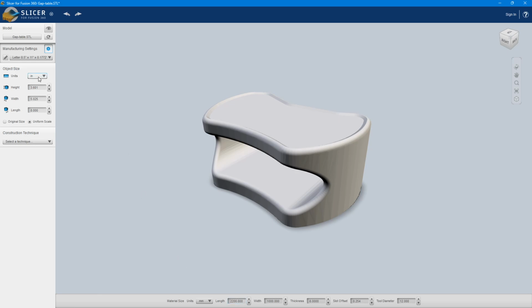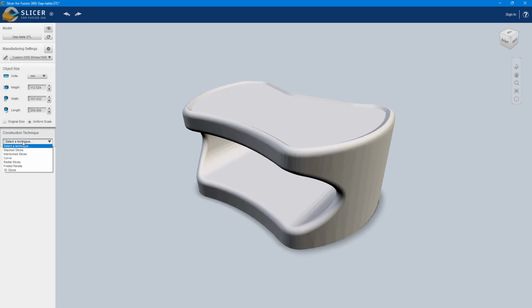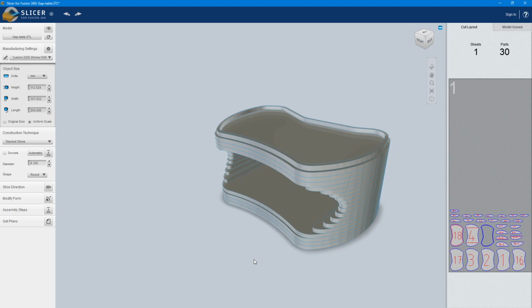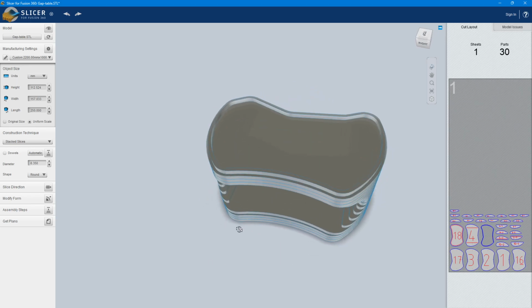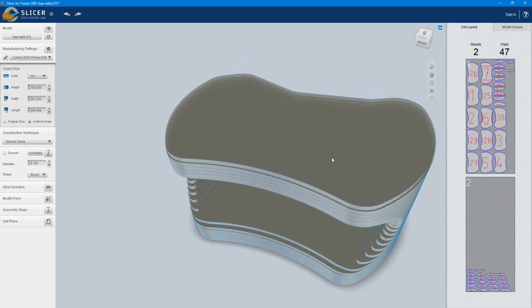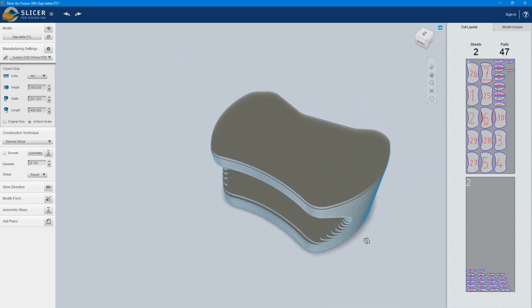Once you have set these parameters, the sheet is there. So now let's change the size of the part. It's going to start with 250, and we want to have the stacked slices. So that's the stacked slices, and you can see at the moment the size is only 250, and our sheet, we need to fill up the sheet if you want to make it as big as possible. So I will change that to 400 millimeter, and the length does not mean this length, it's from here to here is 450. The difference is because of the SolidWorks orientation.